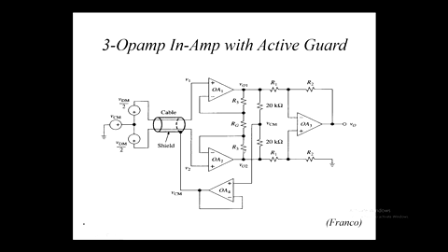Okay, so if we're going to all that trouble, we might as well pick off our common mode signal at the midpoint there, because that's where a common mode signal will be. Good. So we don't need these two resistors. We can just split this one and take common mode signal out from there, providing we don't create more noise in the process. Yes? Sound good? Questions? No? Okay.